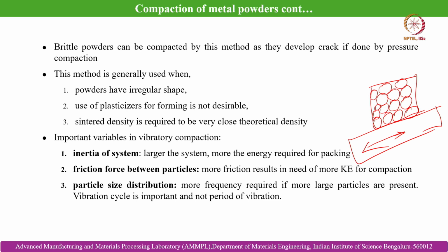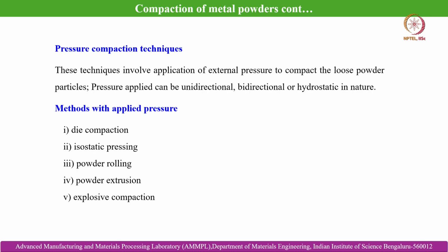Friction force between particles: more friction results in the need of more kinetic energy for compaction. And particle size distribution: more frequency is required if more large particles are present. So, in case of vibration molding of powders, the vibration cycle is more important, not the period of vibration. It is the frequency that is more important and not the vibration time.